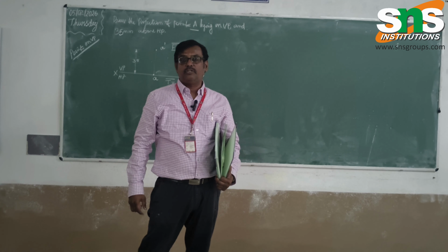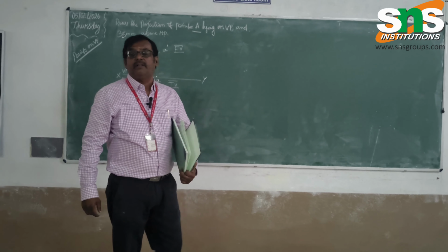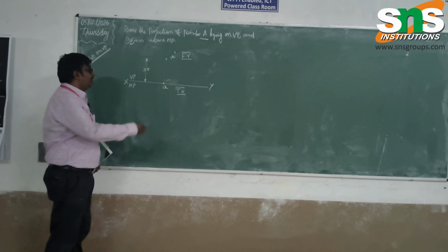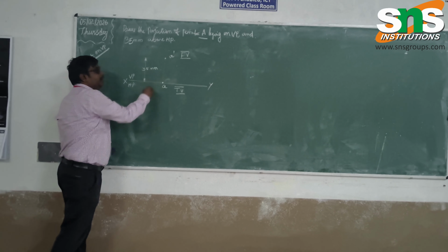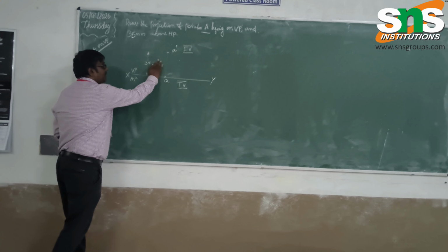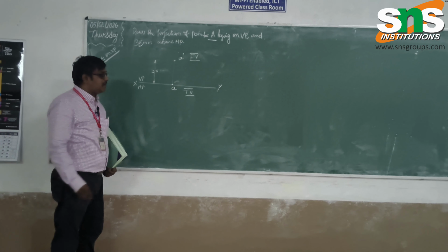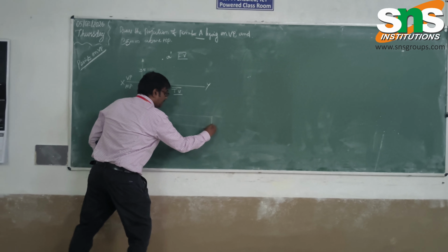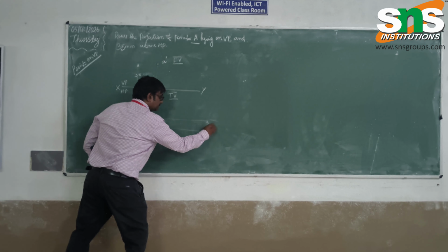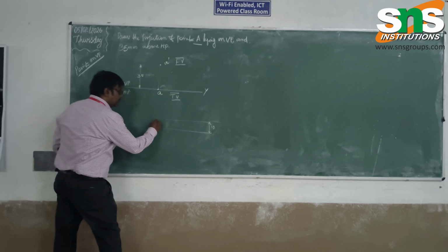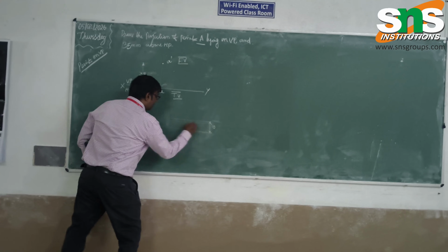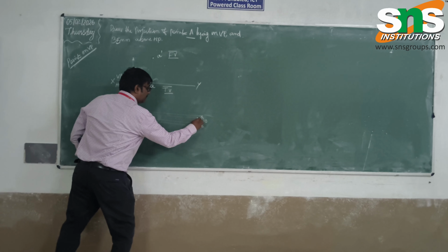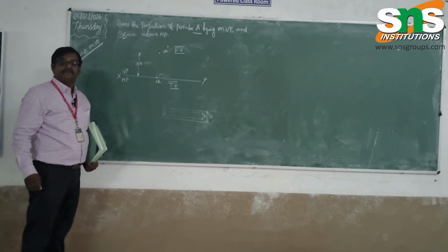2H pencil. Correct. Now, after drawing all this, you may have a doubt whether you have to mention mm, centimeter or meter here. That is not necessary here. As per BIS standard, we have to draw a guideline of 10 millimeter, and in between draw another guideline inside with a distance of 5 millimeter.